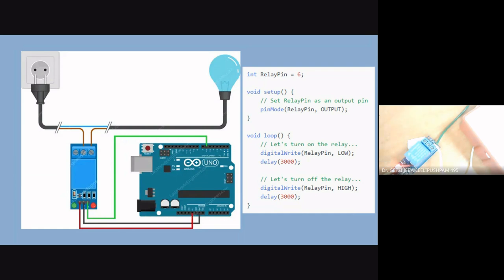Okay, so you can use this relay to even switch on your motors, your water tanks. You connect a small sensor, and if the water tank level is very low, then using a relay you can activate the 230-volt motor. And when the upper level sensor senses that the tank is filling, immediately the same relay can be used to switch off the motor. This can be done.